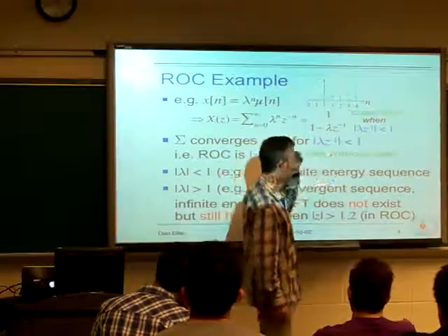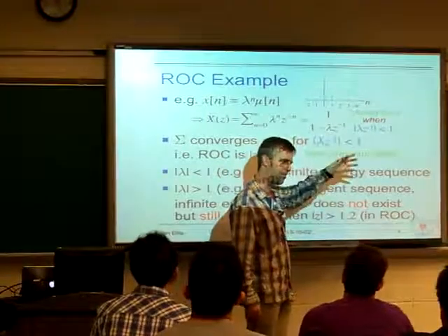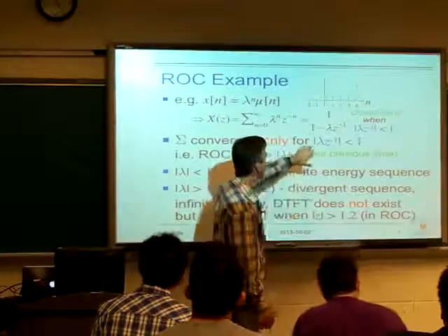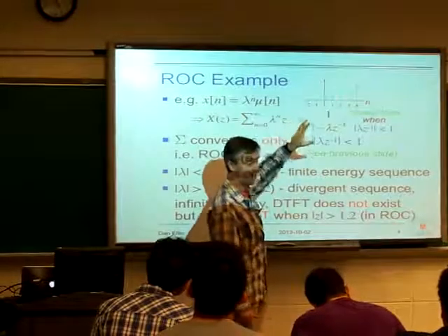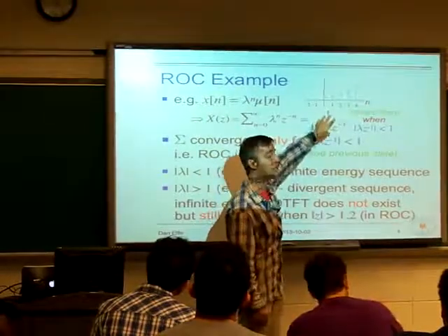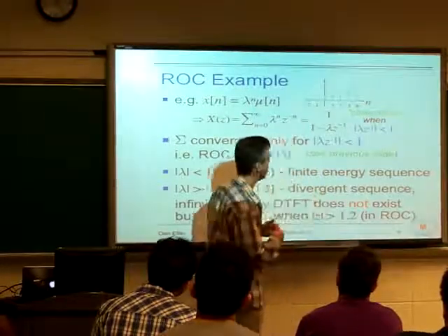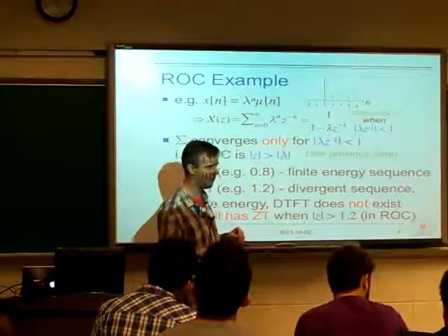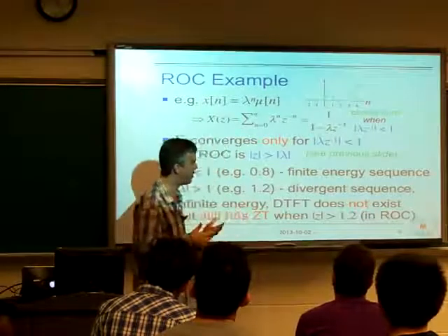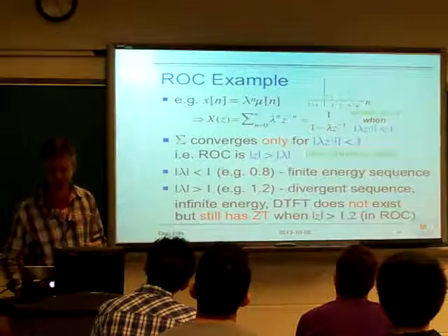And so, the way I was taught this, or the way that I absorbed it when I was taught it, was this is the z transform, and then there's this thing called the region of convergence, which you have to sort of drag along with it, which is somehow part of it. But no, this is the z transform, which includes these values which are unbounded, which are ill-defined. This is a closed form expression which gives us the value of the z transform, but only over some range of values, which is why we have the region of convergence. And that to me is more satisfying. I'm laboring this because it was a big insight for me to think about it this other way around. But maybe that's not a problem you've encountered.